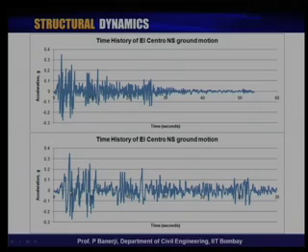Now, that can vary, but typically the strong motion part stays about 15 odd seconds, and then it starts going down slowly, and this is really the surface waves coming, and that is it. Then you start getting very, very low g values, and you do not really worry about it. So, that is how a ground motion looks, and this is the ground motion that we are interested in.